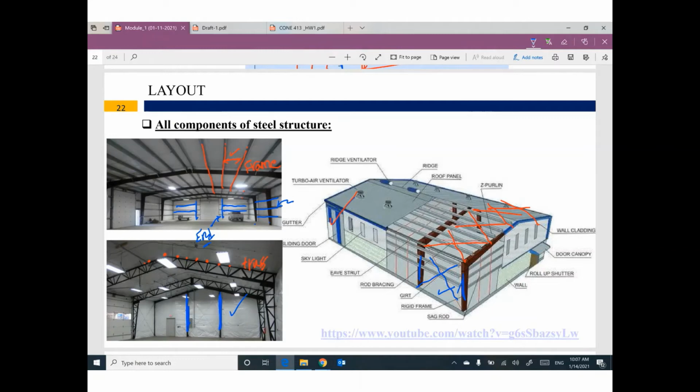At least you have to put 2 panels at the first panel and the last panel to prevent any collapse due to wind. Make sure the spacing between this panel and this panel is 50 to 75 feet maximum spacing. If you have a larger distance, please repeat these crosses one more time inside the building, at an intermediate distance.